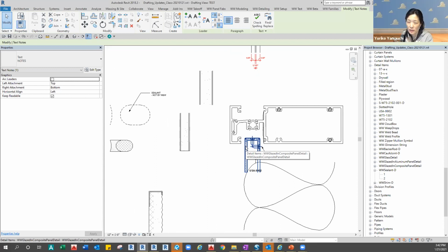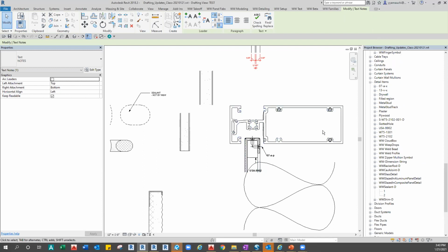So when we place the glass detail family, the gasket comes with it, and then we just select. That's what you're saying? Yeah, turn it on, turn it off, kind of. We kind of discussed it, but so far, you know, the gasket, we have many different ones, and the project has 1 inch, sometimes 1/8, sometimes 1 3/16. So it's really hard to keep every component in one family. So that's why we don't do that. And then usually the gasket is inserted separately, individually.